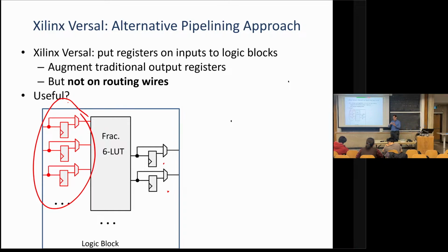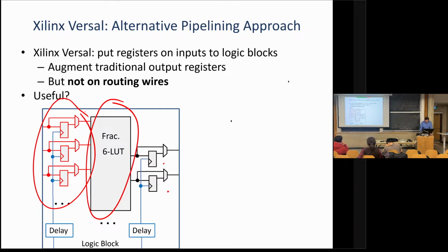And the delay to go through a few wires, depends how far you go, but that's usually going to be the bulk of your clock period. So they can pipeline more deeply, but all they've cut out is essentially the delay through the LUT, right? So the wire delay is going to tend to be the larger part. So it's imbalanced. But then what they did is something clever: they said, well, what we'll do is we'll put programmable delay units on the clocks, okay?